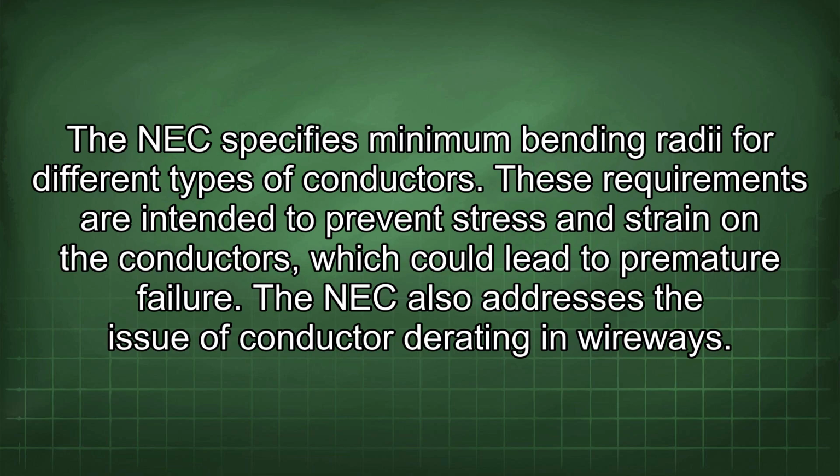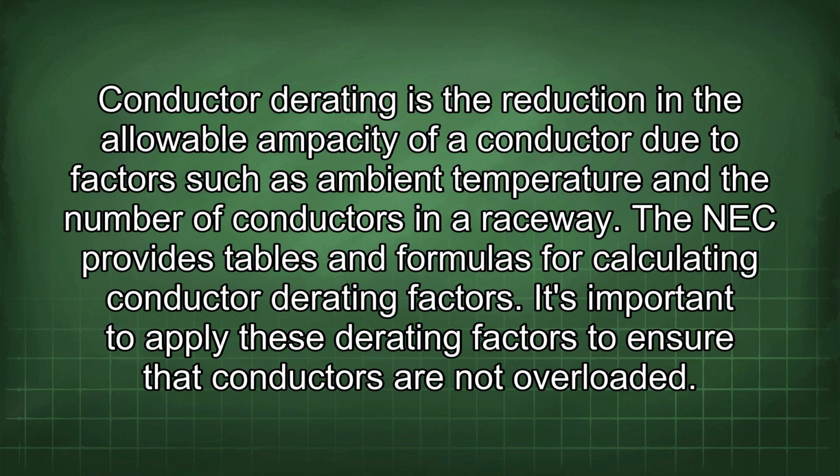The NEC also addresses the issue of conductor derating in wireways. Conductor derating is the reduction in the allowable ampacity of a conductor due to factors such as ambient temperature and the number of conductors in a raceway. The NEC provides tables and formulas for calculating conductor derating factors. It's important to apply these derating factors to ensure that conductors are not overloaded.